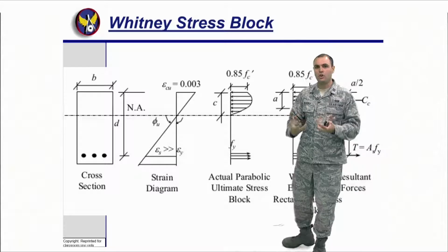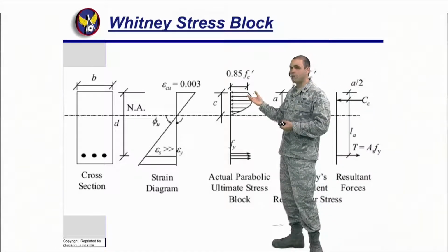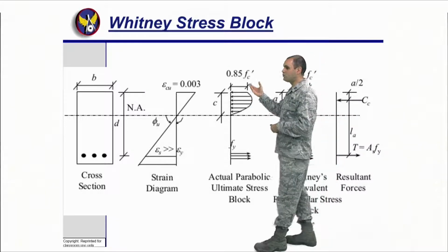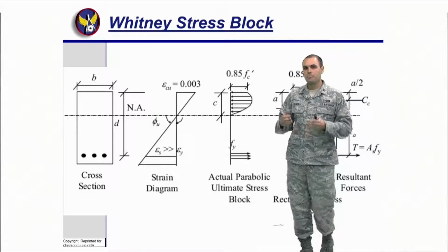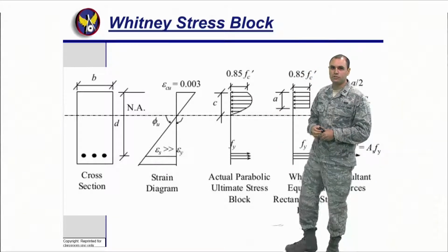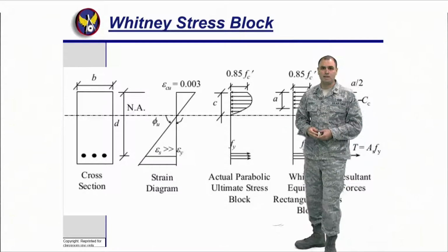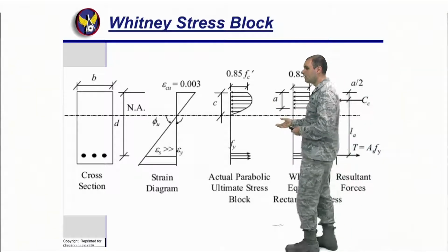The rebar is the only member that's actually holding in tension, whereas at the top, above the neutral axis, the concrete is holding in compression. And we're going to start measuring those distances. And you're going to see this value of 0.85 f'c. f'c refers to the concrete strength. So that's why you start hearing 4,000 psi, 5,000 psi, 2,000 psi concrete. That's what it means.